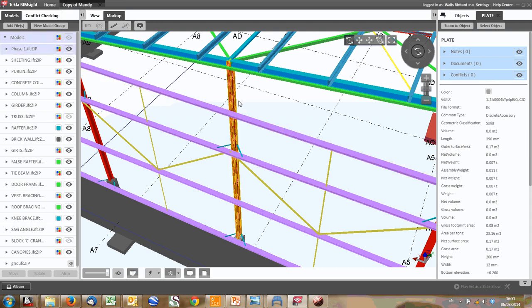So you check your deflection, get your deflection right, whether it's L over 180 or span over 180 or 240 or whatever it is. You can size your member very quickly with a straightforward calc. You can get what your I, your second moment of area, needs to be, and then based on that, you can just look in the book and get a member size that's close enough or just above that second moment of area required.